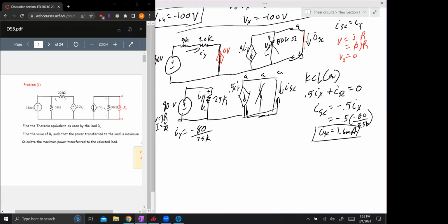Because here's the thing, okay, hold on. This is gonna be really extra. I'm gonna KVL this. If I KVL this, we have an 80 volt rise minus 25K IY equals 0. Negative, wait. 25K IY equals negative 80. IY is equal to 80 over 25K. Minus 80 over 25K, or minus 80.